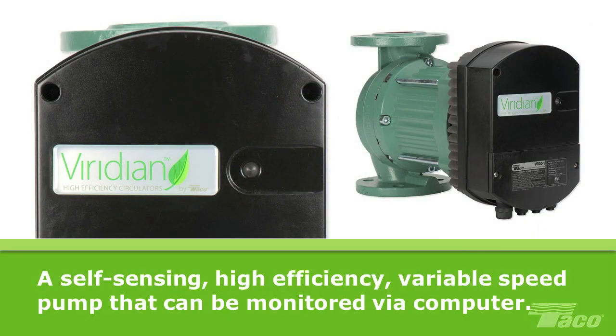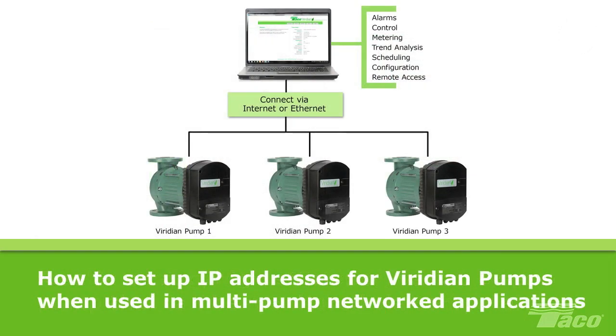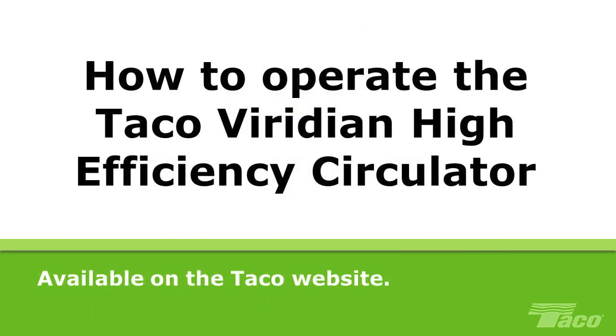The Viridian pump is a self-sensing, high-efficiency, variable-speed pump with ECM motor that can be monitored and controlled via PC or laptop computer. This video demonstrates how to set up the IP addresses for Viridian pumps when used in multiple pump networked applications. For basic instructions on how to wire, set up, and control the Viridian, please see our video How to Operate the TACO Viridian High-Efficiency Circulator, which is available on the TACO website.